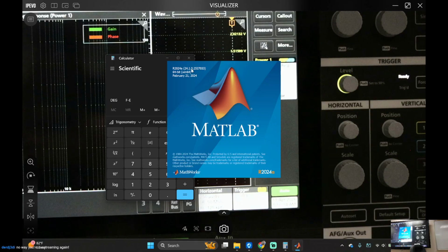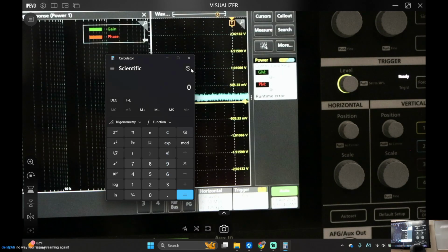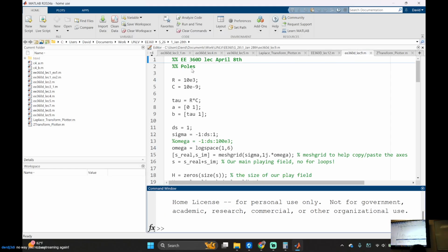So one thing you're going to notice is sometimes the capacitor you're going to get isn't the capacitor that it says it's going to be. So what you're going to do is the following, okay? Grab your alligator clips like this. Plus, minus, and measure your capacitor, okay? Does everyone know how to do that? Yep, measure your capacitor.